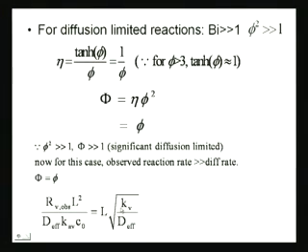So, we are trying to figure out what could be other ways of measuring the observed reaction rate, and this is one of the ways we find over here. You can measure the intrinsic reaction rate, the effective diffusion coefficient, the length of the matrix, and the concentration, and we find a formula to be able to evaluate the observed reaction rate without measuring it. Okay. So, we do not measure the observed reaction rate. Earlier, what were we trying to do? We were trying to solve the whole problem and obtain the concentration profile, which is experimentally very hard to measure.